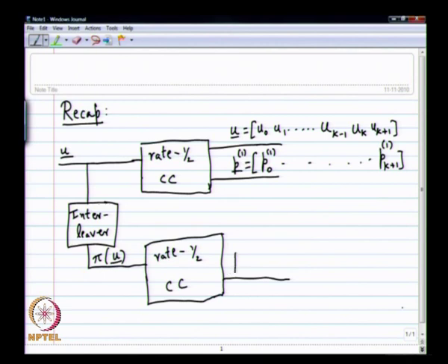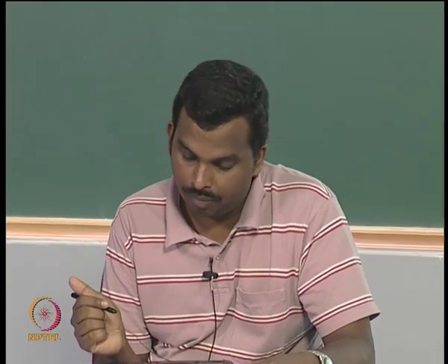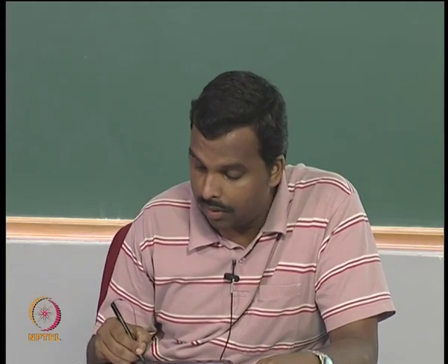Okay. So here you would have again the second parity, which is, let us say, P20 all the way to P2k plus 1 if you want. Okay, so this termination is not a big deal. It is not something that you have to take care of, and it does not change the performance significantly as long as you terminate at least one. It is very typical to terminate the first one and not terminate the second one, okay, and then you are okay.